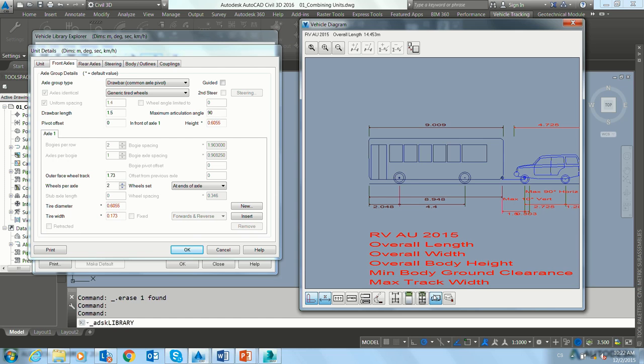Then, more or less, I might be already happy with this. Of course, you can set a maximum articulation angle; 90 degrees is maybe too much, maybe 45. It depends really on the parameters of this towing system, how it will work. And again, you can find different data sheets for this, I believe you call it a tow dolly, and you can find on the data sheets how much it can articulate.